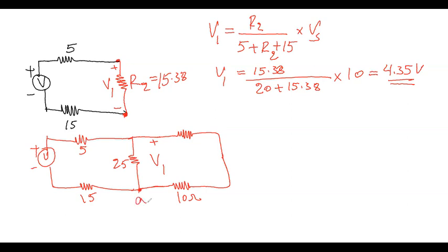This is A. This is B. That's what we're given. And this is a 30 ohm resistor. Now, according to this, the voltage across the 10 ohm and the 30 ohm resistor is V1. Now we can use a voltage division rule to determine the voltage across A and B.